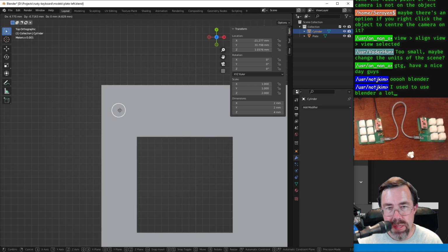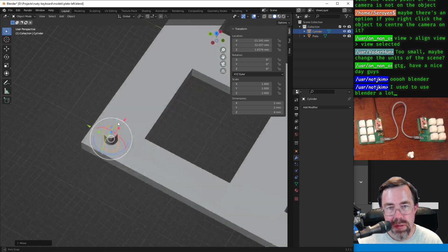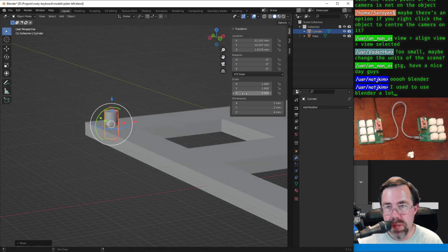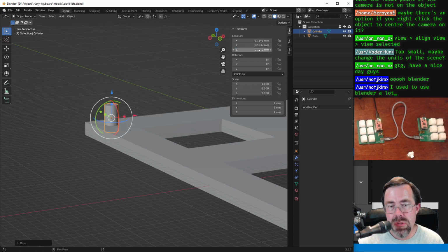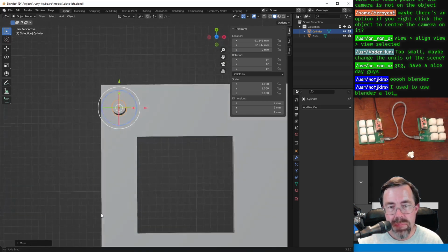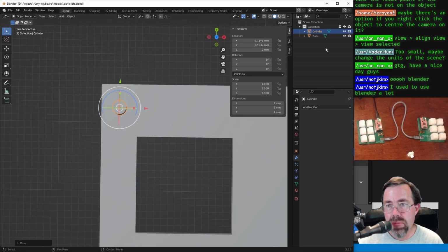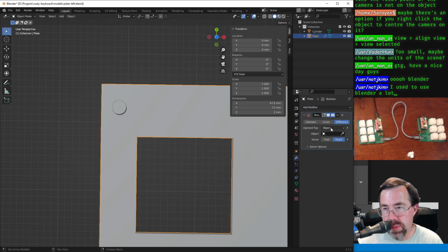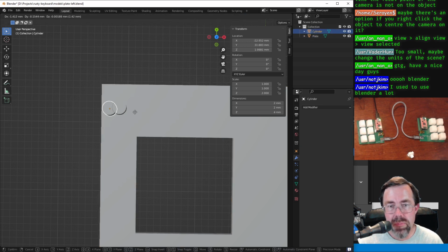I can really place it wherever I want, right? So I could put a standoff there. Let's move it up. It needs to be moved up 1 millimeter, right? Because I need 3 millimeters. There. And then we'll do the binary operator, or Boolean operator. And here we'll do a union with cylinder, apply. Cool, and then we get to move our standoff somewhere else.